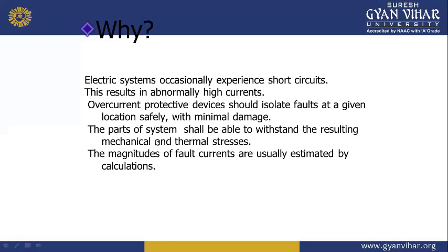Furthermore, from the consideration of mechanical forces that act on circuit breaker components, the maximum current that a breaker has to carry momentarily must also be determined. Therefore, for selecting a circuit breaker, we must determine the initial current that flows on occurrence of the short circuit and also the current in the transients that flows at the time of circuit interruption.